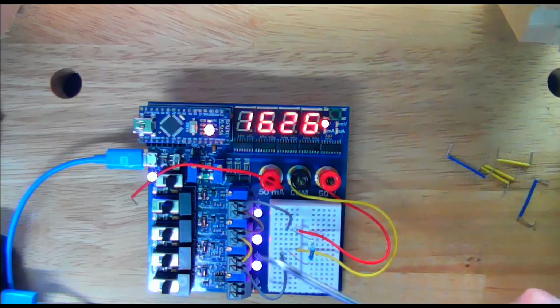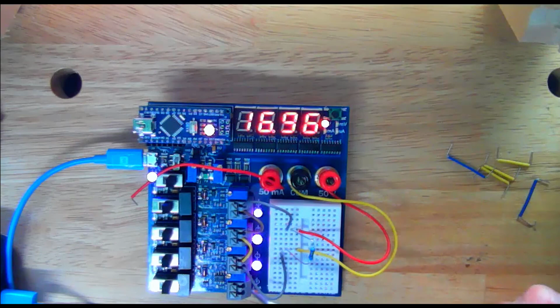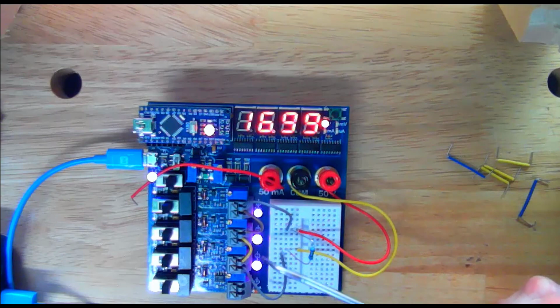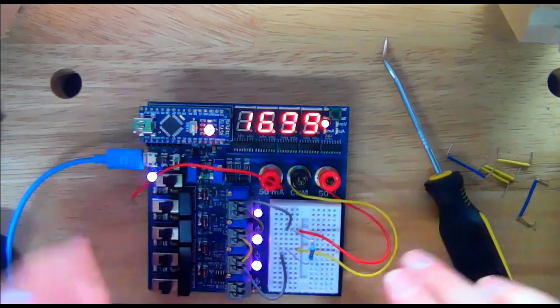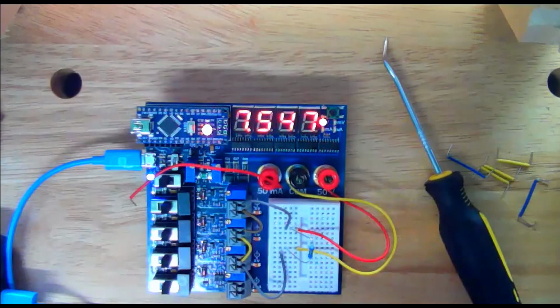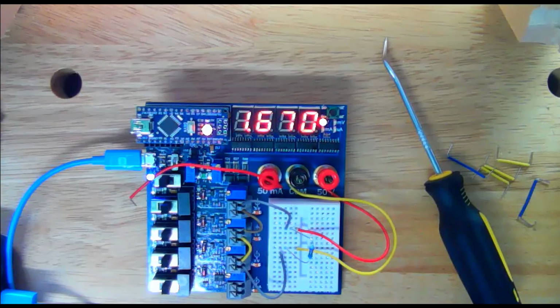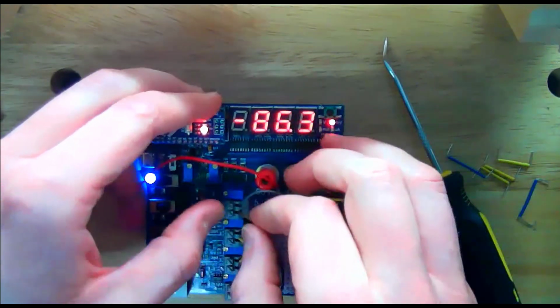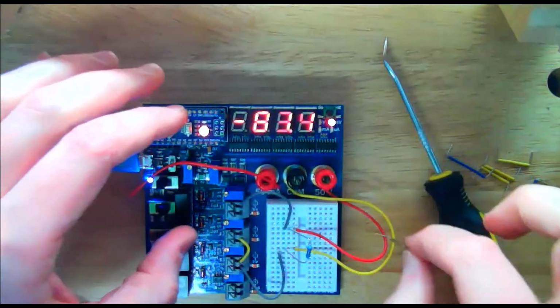So a couple of things. The lights on these supplies are not just for fun. The lights on these supplies are a good indicator for you as to whether or not the supply is working properly. You see a nice illuminated light, it means everything is probably okay with the supply. These supplies do have a little bit of protection, so always check your circuit before you connect it. Make sure your circuit's correct before you energize it. But these supplies do have a minimal capability of, if they encounter a short circuit or something that could possibly damage them, they do have a little bit of protection, a little bit. It is still possible to break these.